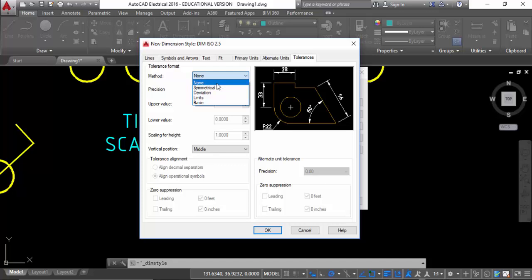I'm going to give you an example. If we take steel, for instance, we will drill a hole into the steel, but we'll make it 2 mil wider than the bolt that goes into that hole. Okay, and the reason why we would make it 2 mil wider is because if I'm going to drill it to the exact size of the bolt, if it goes to site, if there's a little bit of heat on site, or let's say for instance it was extremely hot inside the workshop and now you've drilled it to the